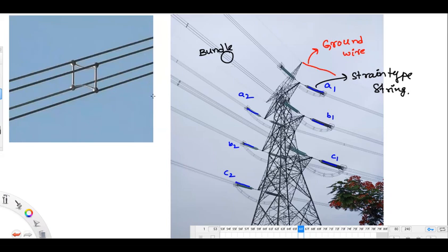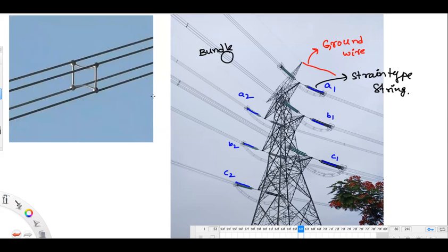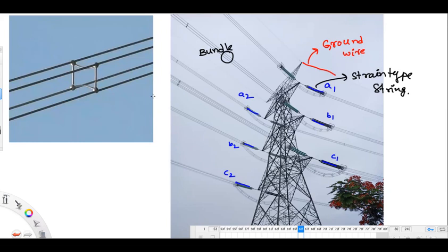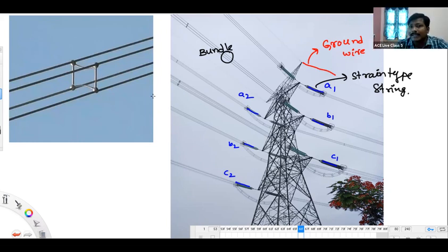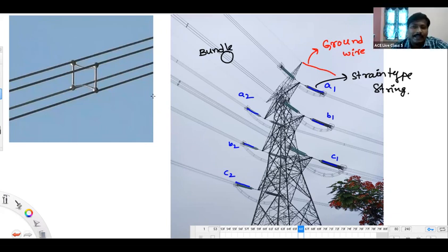Another doubt. For high voltages there is an extra loss from corona, so why do we go for high voltages? For bulk power transmission as well as good stability. But we are getting an extra loss term. It doesn't matter, by using bundle conductors we are reducing it. For example, if you want to transmit 1000 megawatt power, how many 132 kV lines would you run? Many. Rather than that, one 400 kV or 765 kV double circuit line might carry the whole power. The cost of the system will be heavily decreased compared to that many circuits.